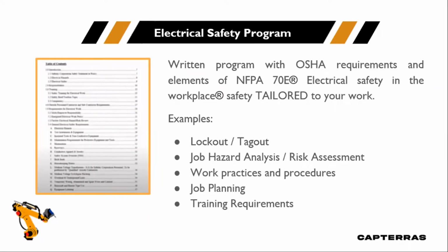Electrical safety program. Every workplace must have an electrical safety program. This program must be written in accordance with OSHA requirements and elements of NFPA 70E. Electrical safety in the workplace: safety tailored to your work. Some examples are lockout/tagout, job hazard analysis, risk assessment, work practices and procedures, job planning, and training requirements.